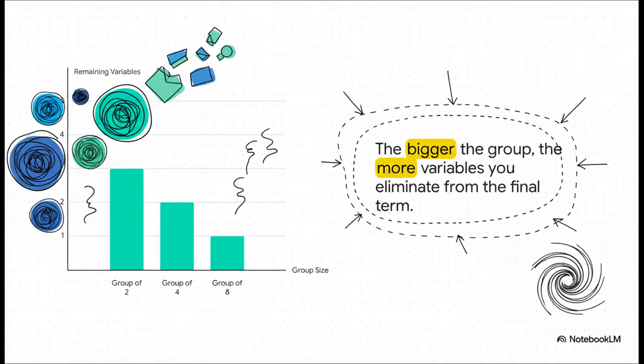And here's the payoff for making those big groups. It's simple. The bigger the group, the more simplification you get. A group of 2 ones gets rid of 1 variable. A group of 4 ones, that gets rid of 2 variables. A group of 8 knocks out 3. The bigger the loop, the simpler your answer.